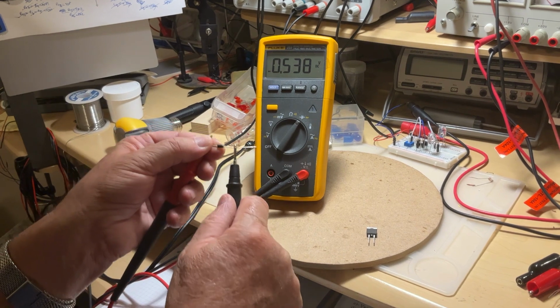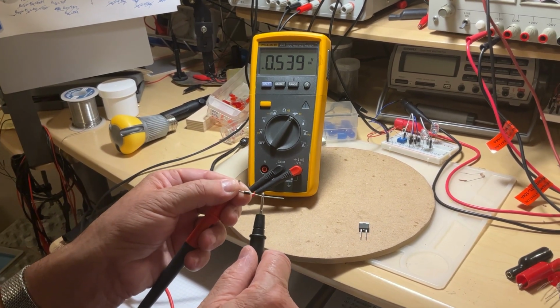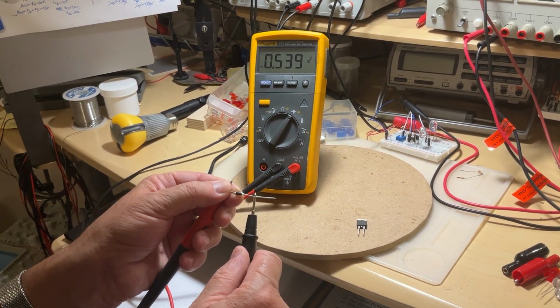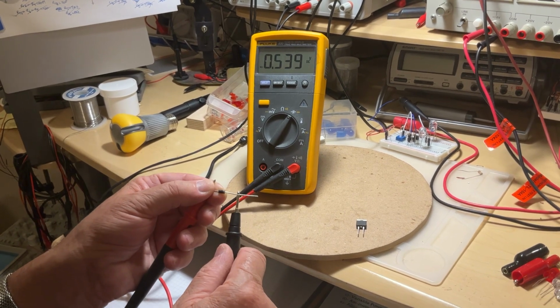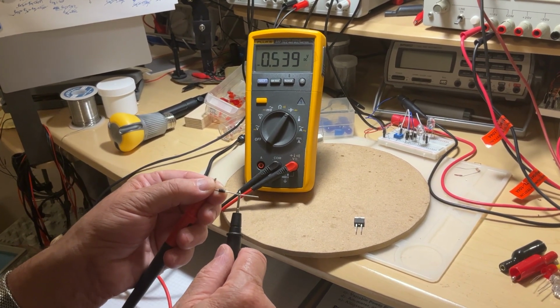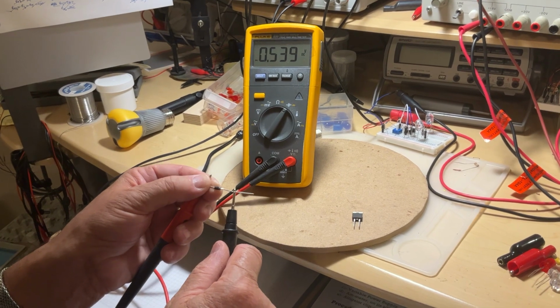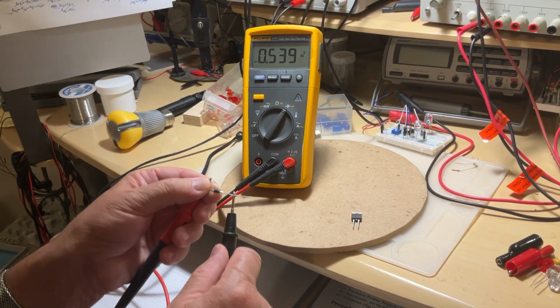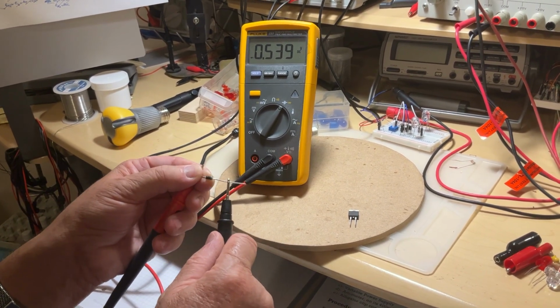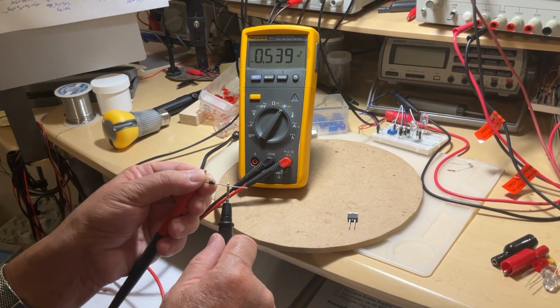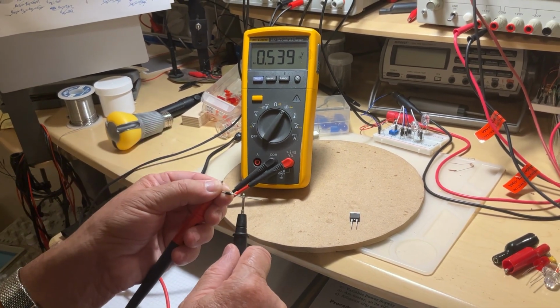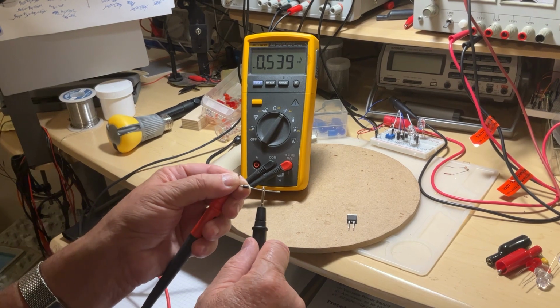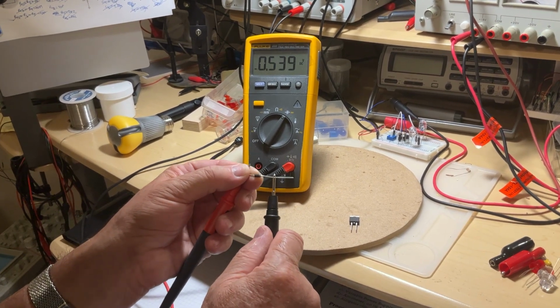And you're going to see some indication on the meter. The indication is not very relevant, but if you use the same meter all over again, you're going to become used to these numbers. Why is the indication not very relevant? Because the number may not be the same if you use another kind of multimeter. However, because I use this multimeter for a long time, that's the kind of number I'm going to see when the diode is made of silicon.